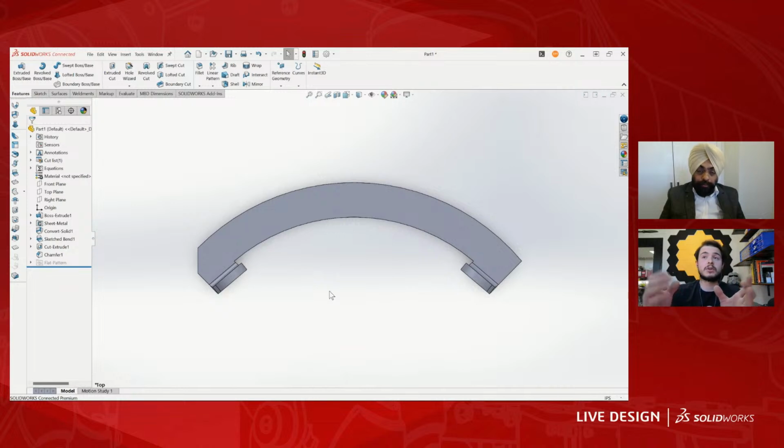So you can laser cut a piece of acrylic, heat it up with a heat gun or a blowtorch, put it over the edge of a desk and bend it down. And now you have the same geometry as if you would 3D print this entire section. But it's very, very quick. And acrylic, you can also glue together very easily and very strong using acetone, which makes it easy to join parts together without using super glue or hot glue, making very clean parts. And they can be transparent as well. You can use these as light diffusers. You can engrave these and have different designs in that without adding any extra process time.